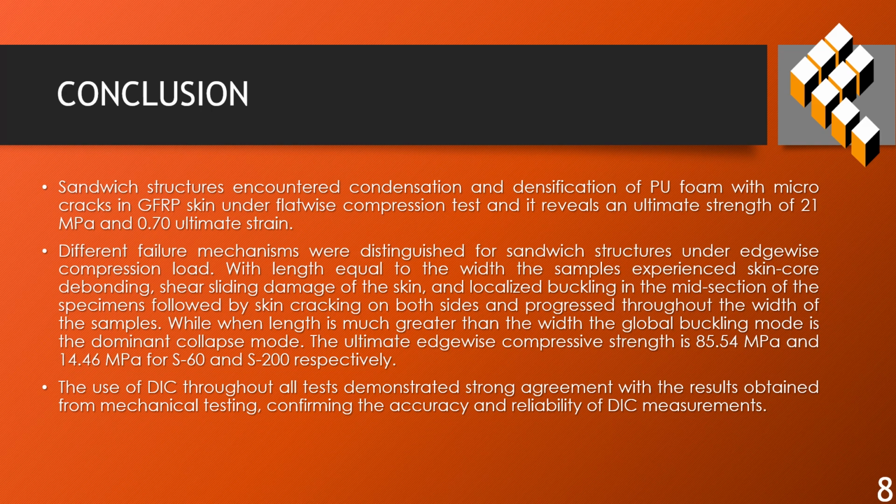In summary, the sandwich structure with GFRP skin and PU foam core showed diverse failure modes under compression. Specimen geometry significantly influenced edgewise performance, and the DIC results aligned well with mechanical testing, confirming its accuracy.